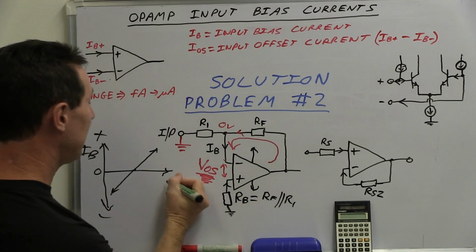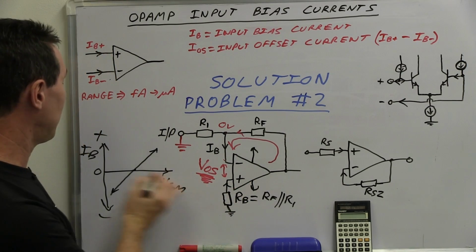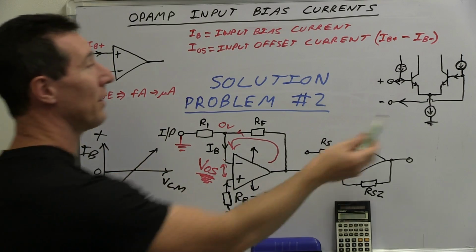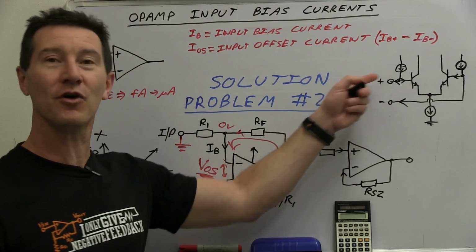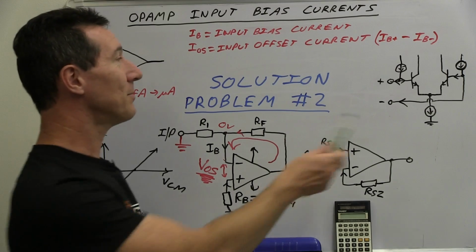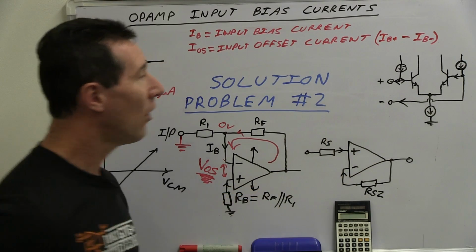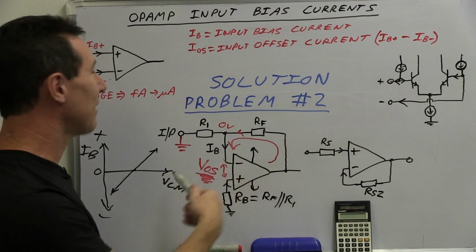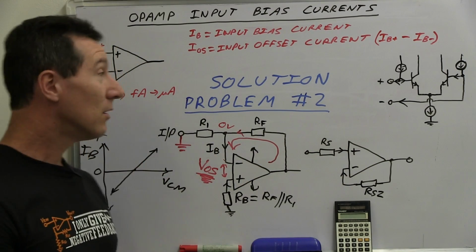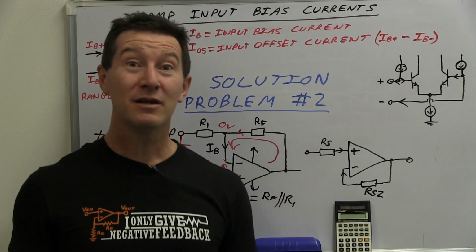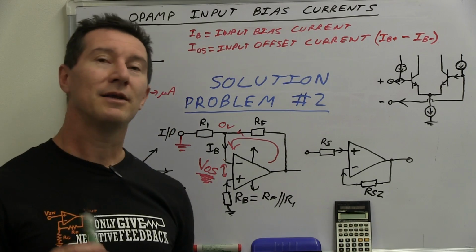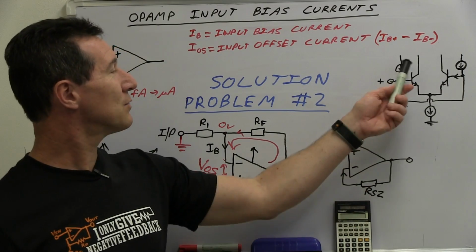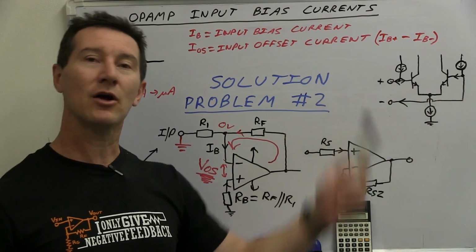The common mode here, that's V common mode here, depends on what input configuration, whether or not you've got an input bias compensated or rail-to-rail op amp, the supply voltage, all sorts of stuff, and which configuration you're using, your source impedance. Oh, and we haven't even mentioned temperature. So how do you know if your op amp has one of these input bias compensator values?